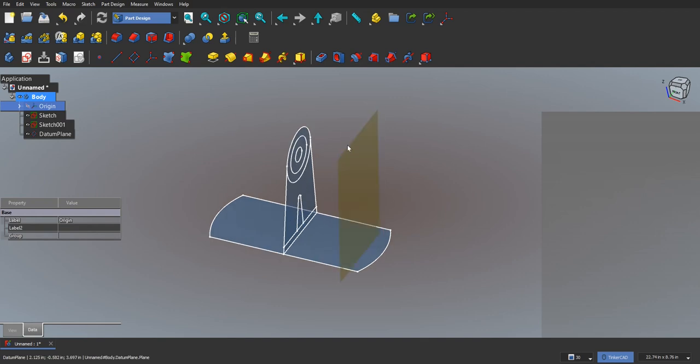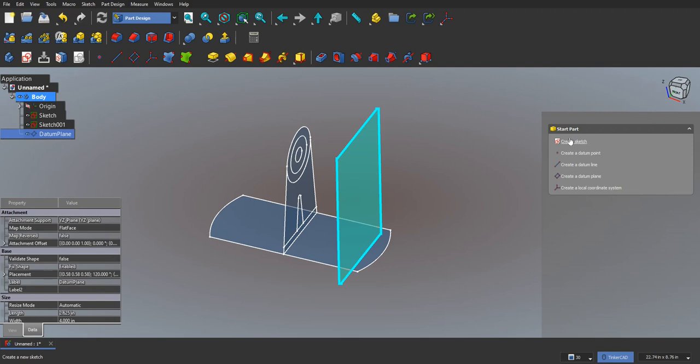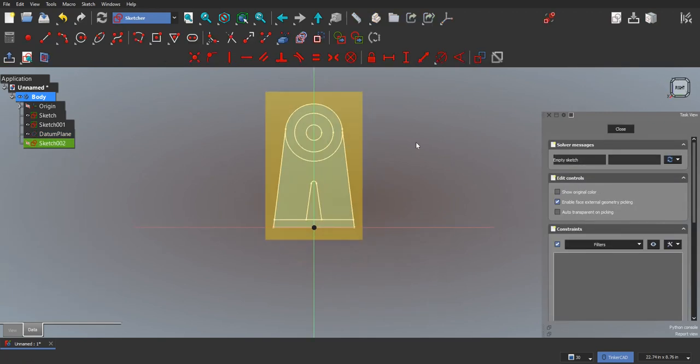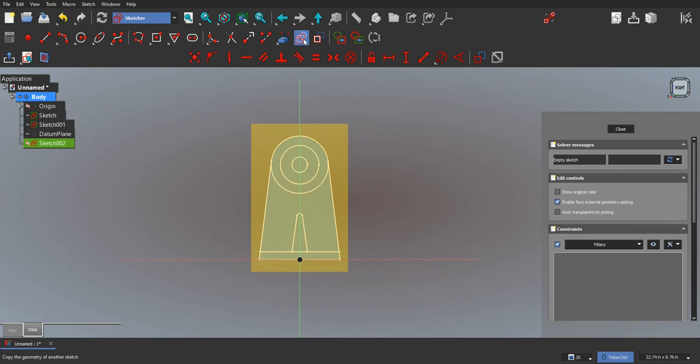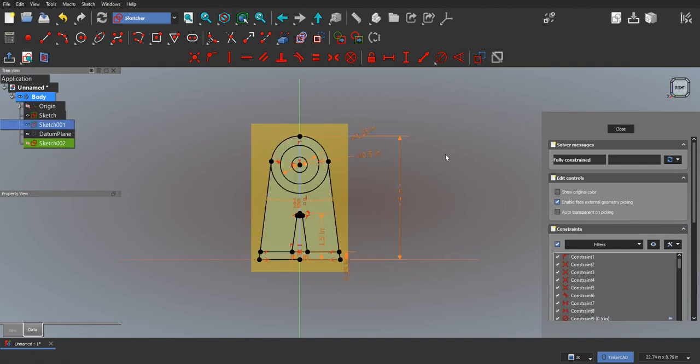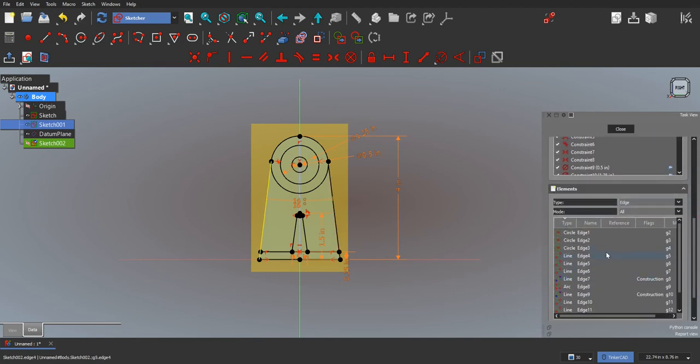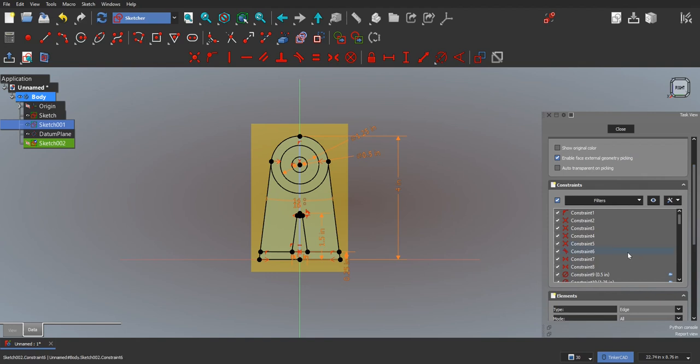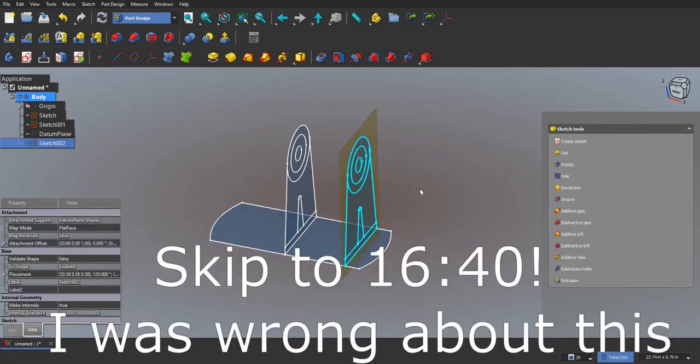And what I'm going to do is create another sketch. I know I said we're done sketching, but I'm just going to create a carbon copy. So I'll click on this sketch, that's what we want to duplicate, and it just makes a derived sketch, and all of these are orange now, and what that means is that they are linked to that original sketch. So if I change a dimension in there, it will update in here as well. So that's one way of doing it.